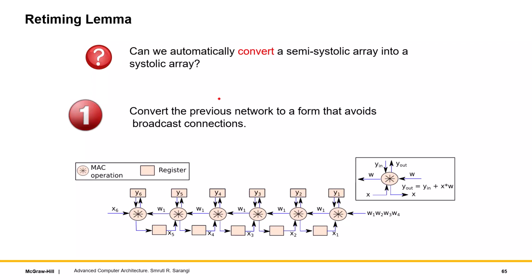So it turns out that we can do something like this. So let's look at it. What we can basically do is send the weights from the left, and we can send the inputs from the right, and hope or expect that they would collide with each other at exactly the right points of time. And this unit over here will make it more special. So in this case, what will happen is that the weights will keep getting transferred this way. And the inputs, however, will not get transferred this way, they'll get transferred via a register.